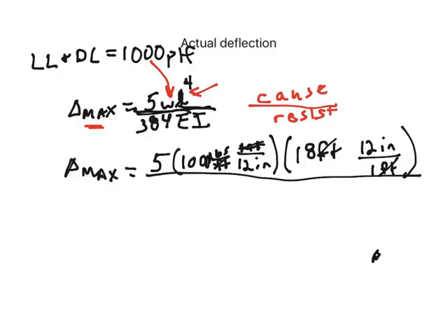And it's a good thing that the top requires so much room, because underneath we have some really, really big numbers. We have the 384, and the modulus of elasticity for steel is 29 million. That is the resistance of the steel to bending. Then I've got the I value, which I have to look up, which is the resistance of that W12 by 14 beam. So we're going to go back to structuraldraftingnet.com and look up the moment of inertia for the beam that we were looking for, that W12 by 14. So let's look at that table.